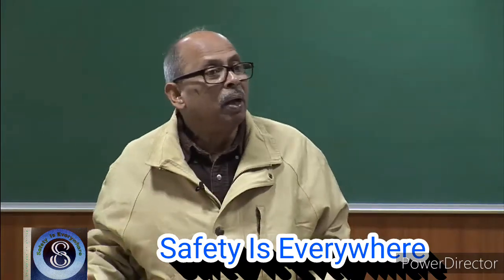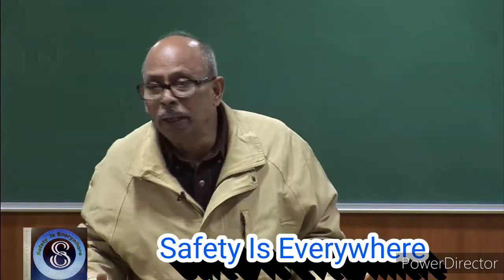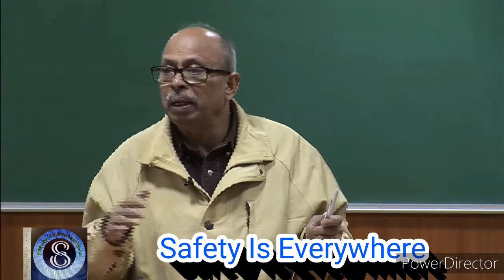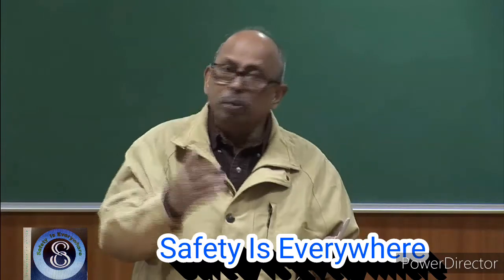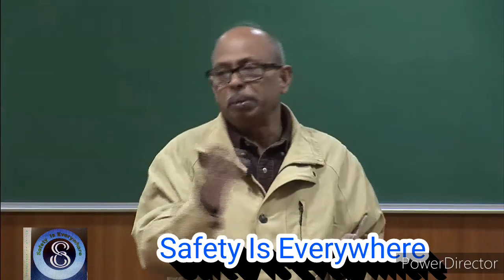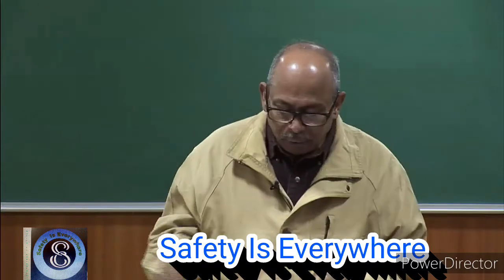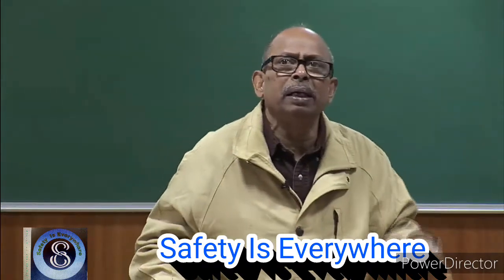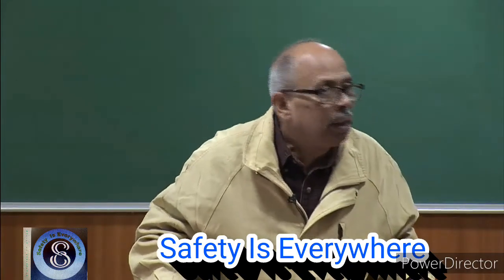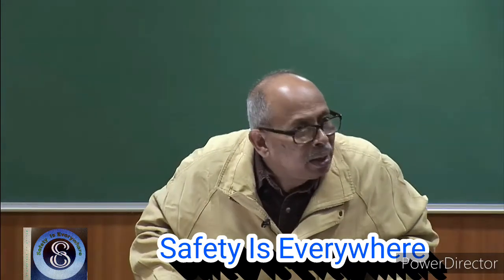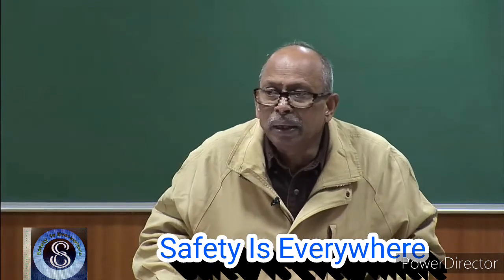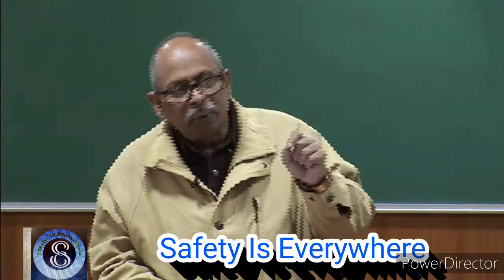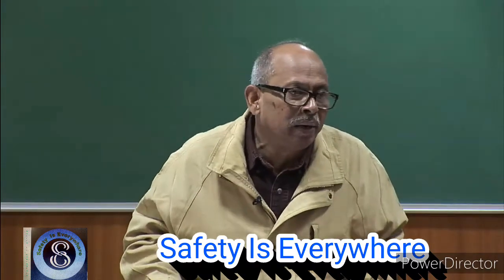If the material has a lot of deformation capability, that is ductility, the system can deform before failure, and then it will give an indication. But beyond a point it is not acceptable, it might go to the plastic zone. So stability is defined, as normally done for a slab or a beam, in terms of maximum deflection related to the span or the span-to-depth ratio. So it is related to that criterion, the deflection or collapse.